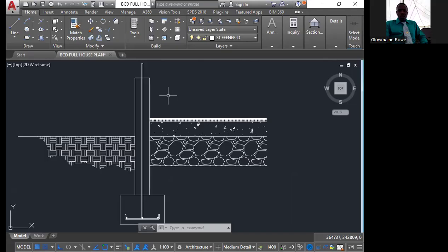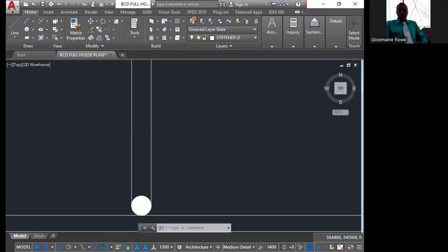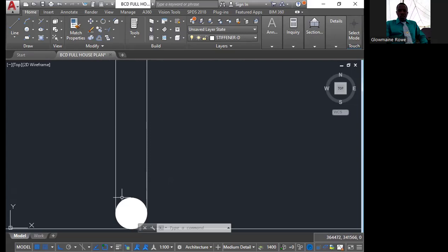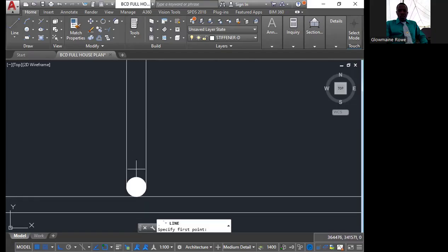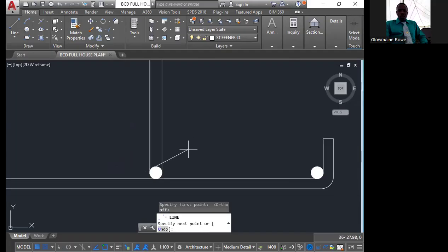Alright, so we're gonna put a hook shape. Alright, so select the line command. You're gonna turn off your auto mode. Now at the top of this steel bar here, top quadrant, click. Alright, better yet, let's draw it horizontal and then rotate it to an angle.